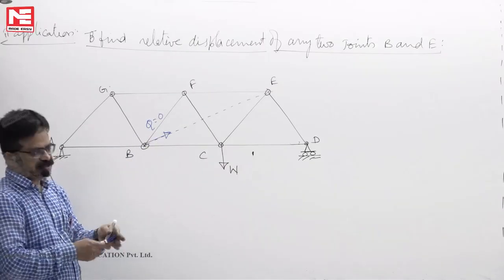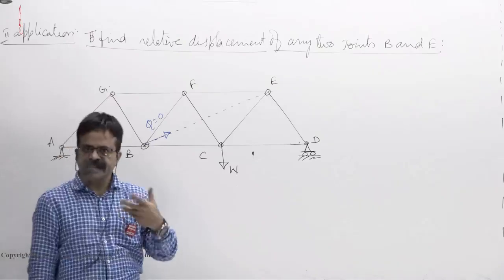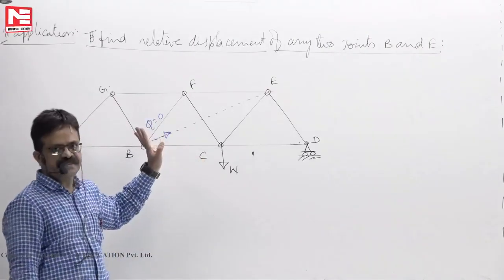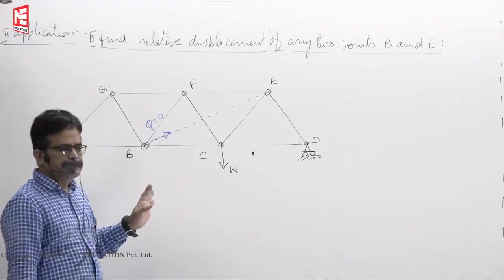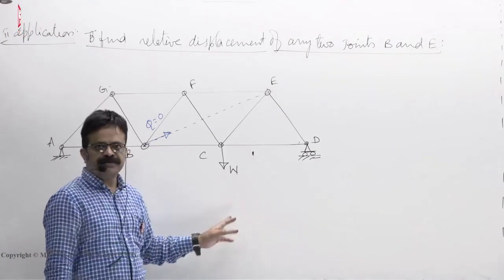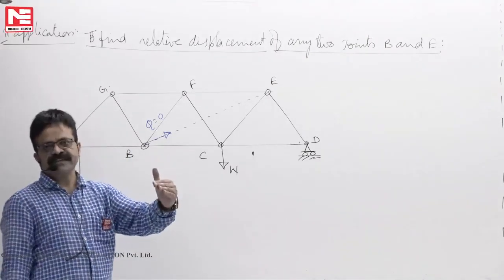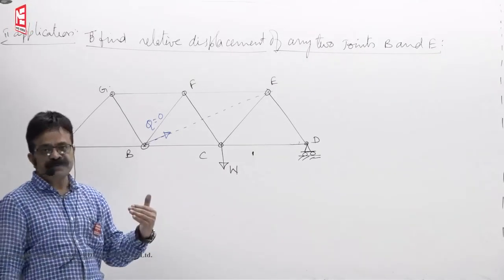And in the strain energy, when you are finding all the loads that you are expecting to act, you must apply them simultaneously and calculate the deflection or calculate the energy. First apply load W, find the strain energy. Then apply load Q, find strain energy. Adding individual strain energies is not possible, because strain energy U is equal to W square L by 2AE.